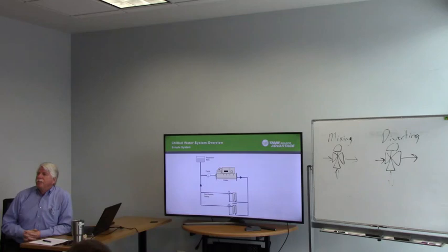Okay? Then the next thing is how much more static pressure will it take to do that? To raise it 10%, that's a square relationship. So that means it'll be 1.1 times 1.1, or 121% as much static pressure.